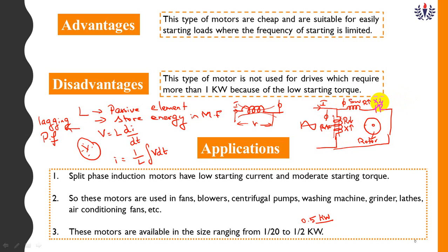When the switch is closed, the motor will start. It starts running slowly, and you have to vary the voltage up to the 220 rated voltage using the auto transformer. Once you achieve the rated voltage, at a particular moment the centrifugal switch should be opened. Then there is no supply to the starting winding, so it is automatically disconnected.